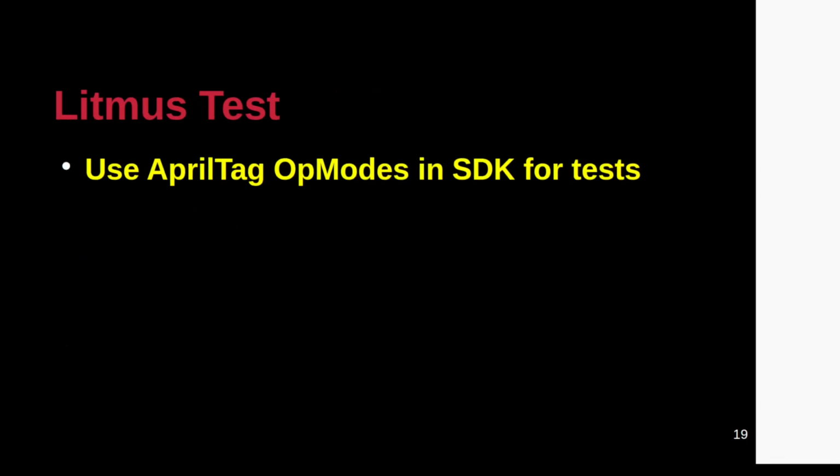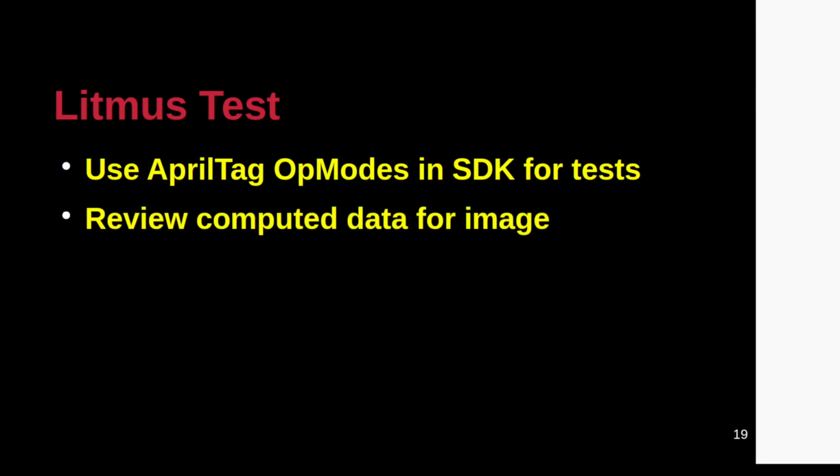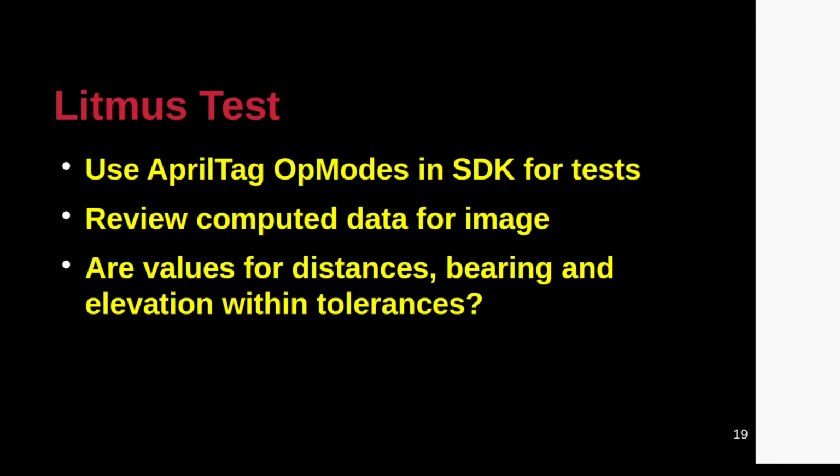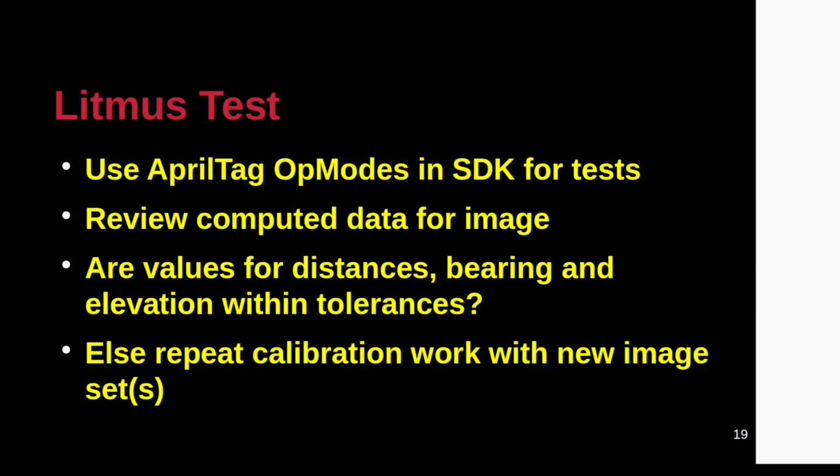This is where the rubber meets the road. Transfer the calibration results to a basic OpMode for validation. This can be done either by updating the resource file team webcam calibrations.xml or passing the coefficients as parameters in your OpMode.